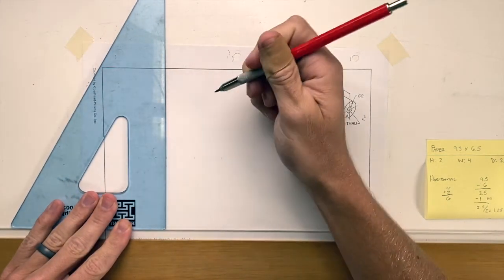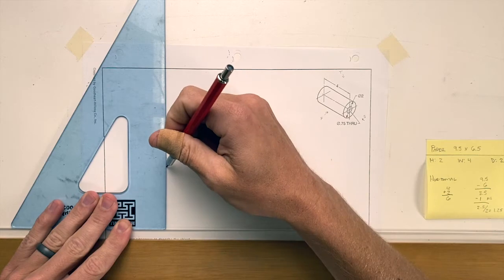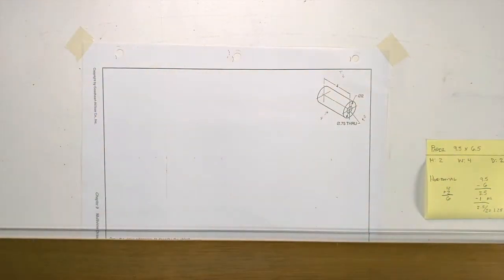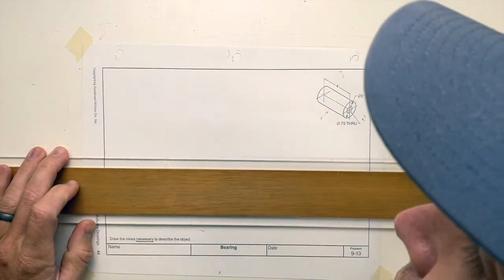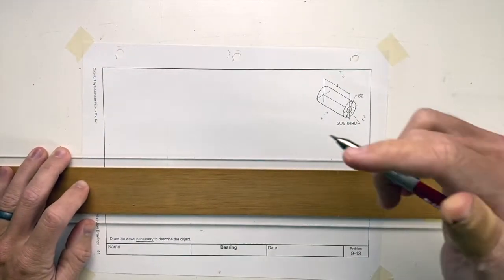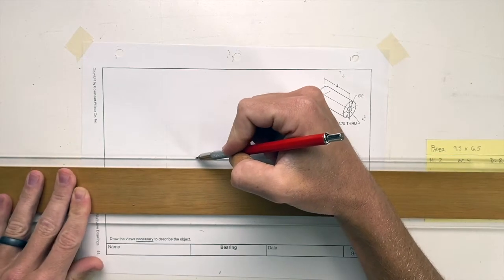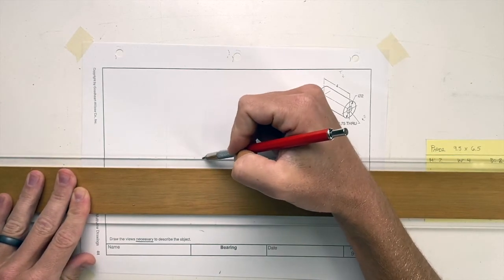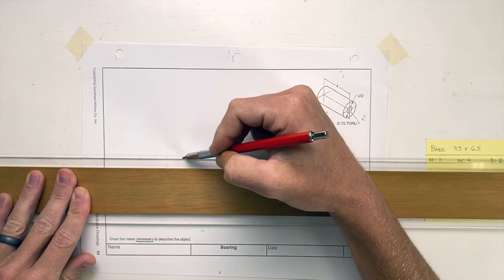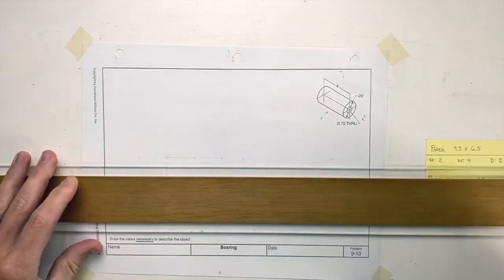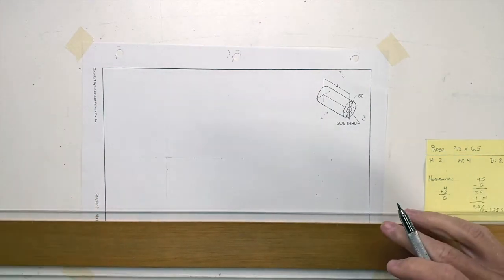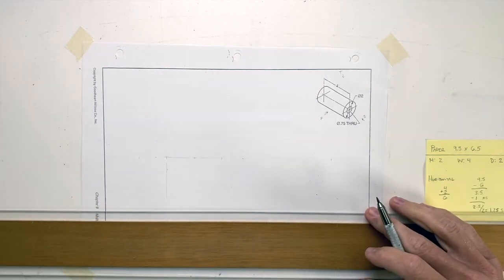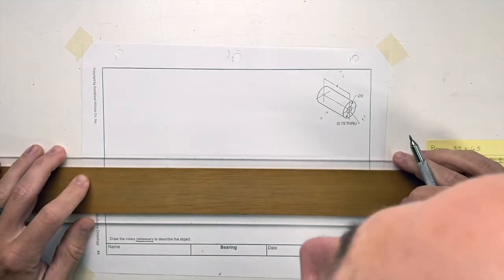So small dash in the middle, long dash, long dash. These are very, very light lines. I'll trim them up later. But for my horizontal direction, I've already actually measured, so I know where to stop them. So small dash, long dash just beyond my 1 inch, like so. Sorry, I drew those in the wrong place. Well, let me fix that now.